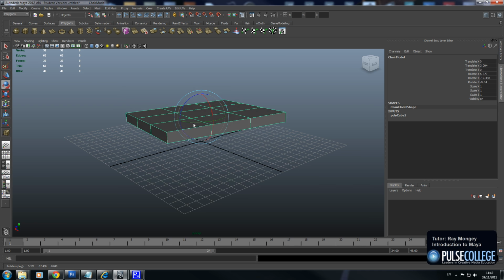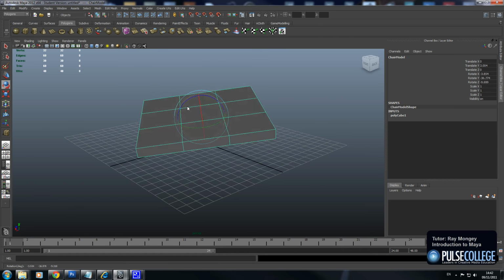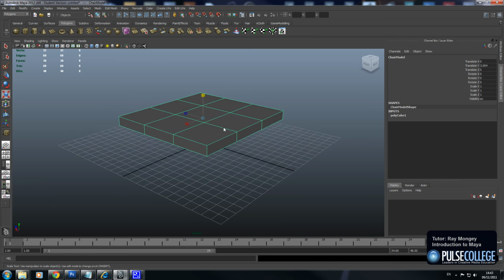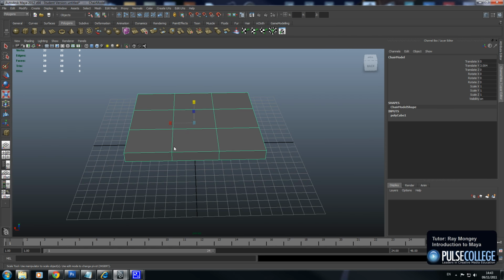As you see in there, if you drag it in the center, it's going to rotate it in all three at the same time. Sometimes helpful, most of the time not, so maybe forget about that for the minute. The R key will bring us to scale, so hitting the R key, and now we can actually scale the object. I'm going to undo that for the minute. Now basically I want to move all these edges out to the side and all these edges out to the side, and the same for these guys here.